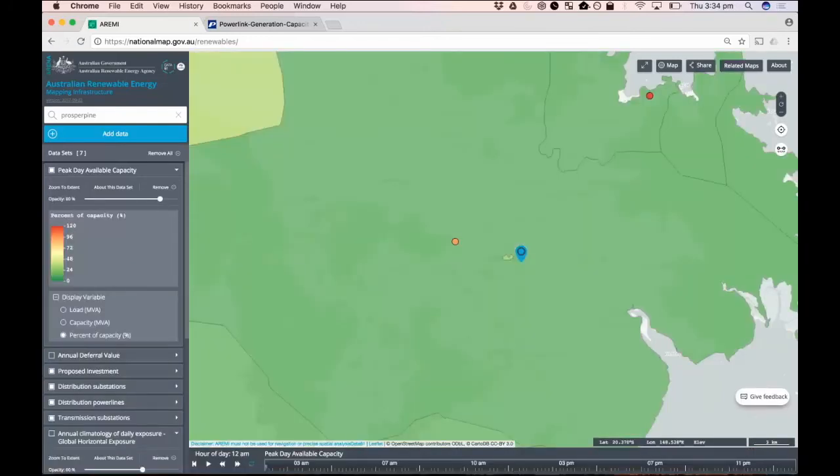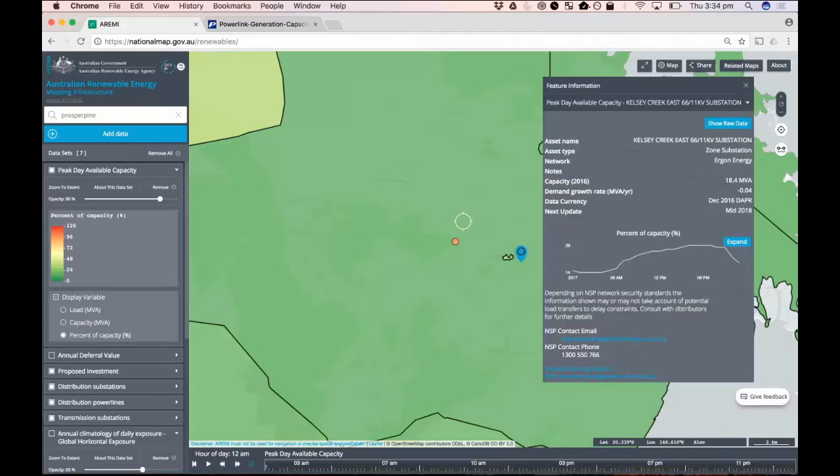But if you click on this region, you can see the load curve that's associated with that particular constraint. And so you can see that it's a really long constraint. It's actually quite a broad peak, which is indicative of a transmission network issue rather than a peakier distribution network issue. And so that extends into the evening, which might mean there might be a role for battery storage, or it might actually be something that's potentially more suitable to a bioenergy dispatchable generation case.